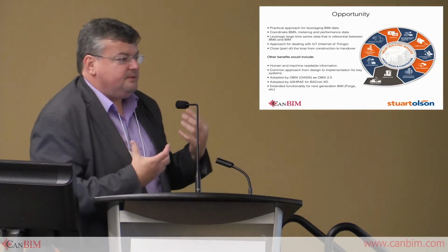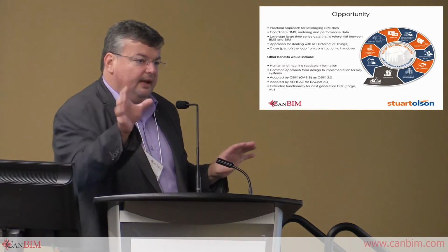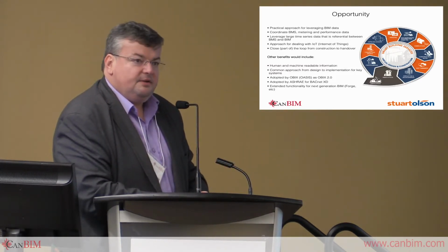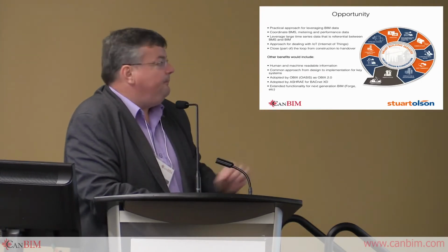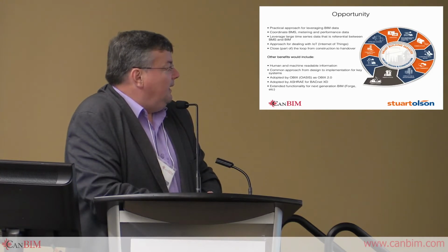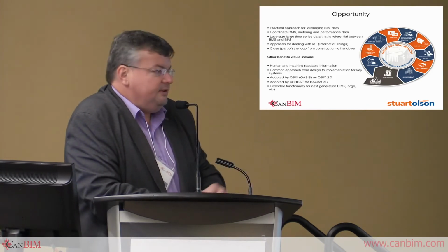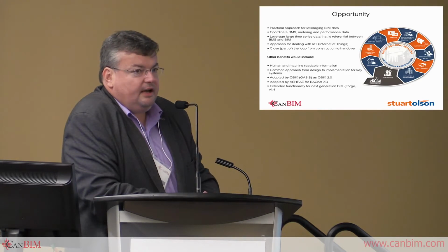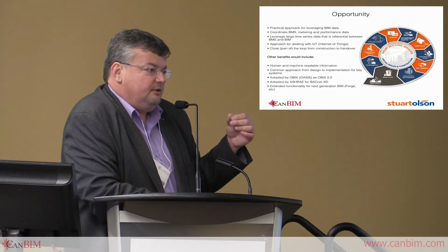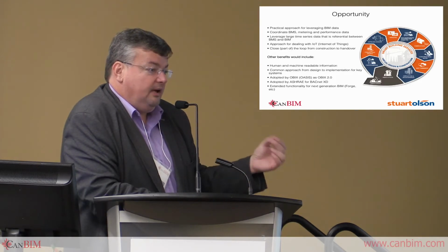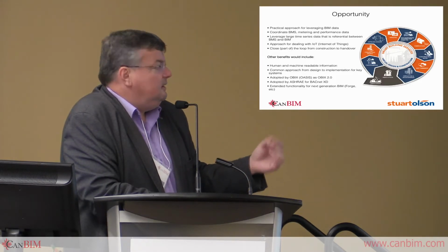IFCs do not lend themselves well to storing huge volumes of real-time data, right? So this would be one mechanism to help enable augmentation with other systems that can handle 3 years of energy consumption data, for example, but yet have it tied to BIM. Probably the other benefit too is human and machine readable. The Haystack protocol and technology allows you to develop something that a human can read, but a machine can read as well.